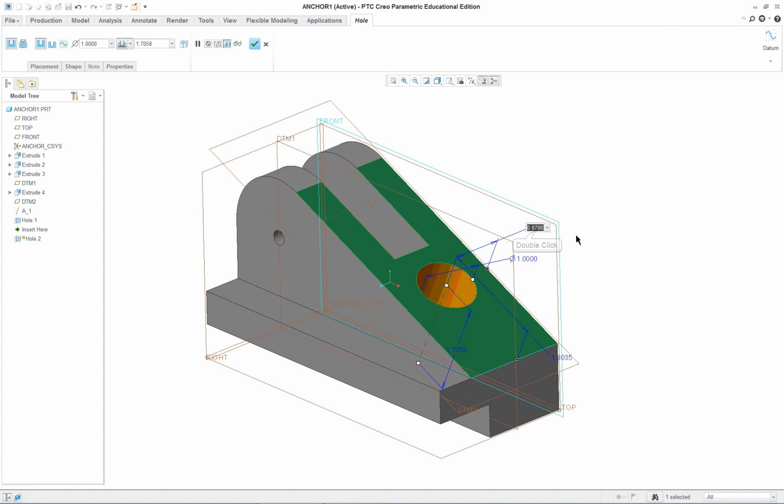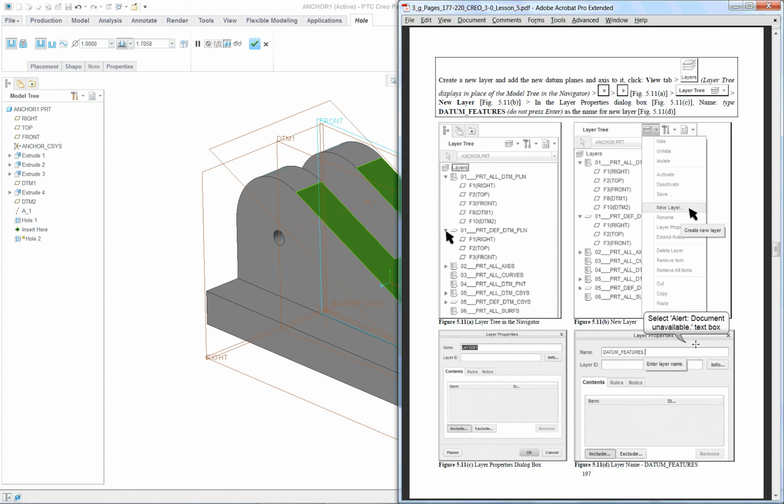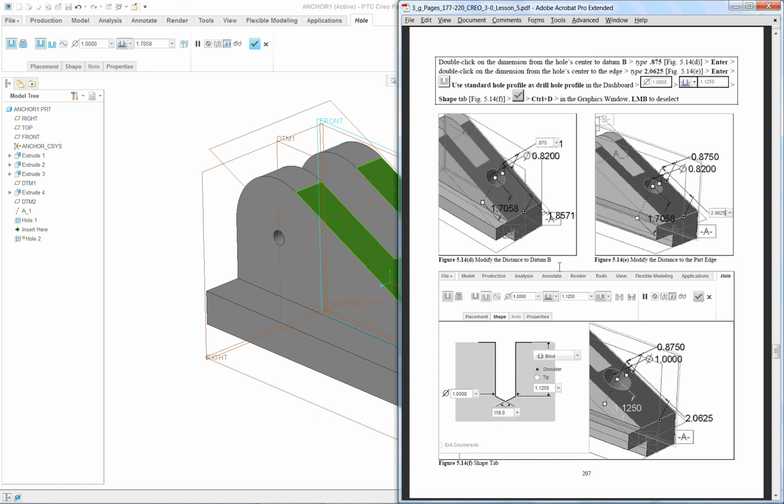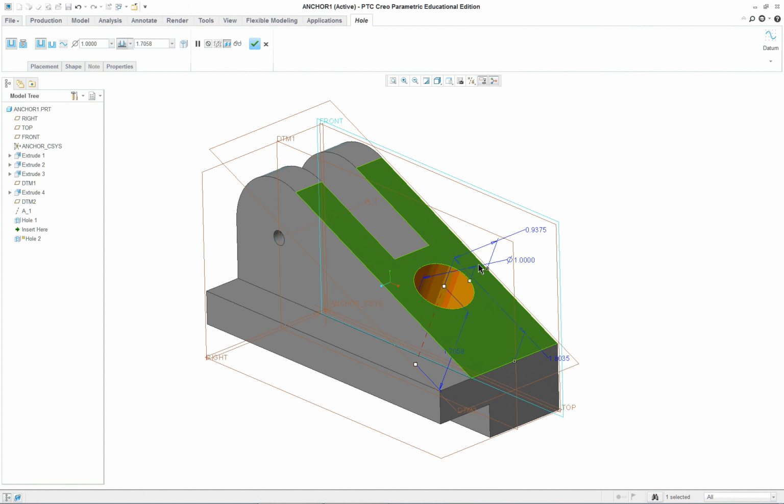Now I know this dimension here is going to be 1.875 divided by 2, and I know this other dimension here, and we'll see what that one is for the hole. It's not going to be a threaded hole, it's just going to be a regular hole. And basically I have you go 2.0625. Let's try that for the dimension. Oh, didn't do it right. Watch when I'm typing.